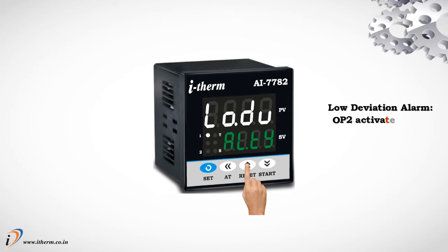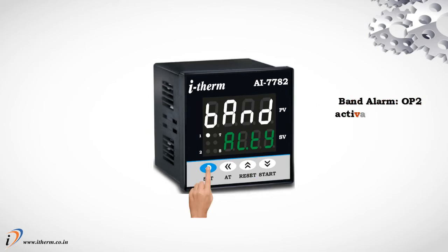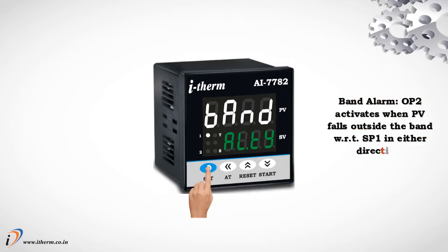Low deviation alarm. Output 2 activates when process value is less than setpoint 1 plus minus set deviation value. High deviation alarm. Output 2 activates when process value is greater than setpoint 1 plus minus set deviation value. Band alarm. Output 2 activates when process value falls outside the band with respect to setpoint 1 in either direction.